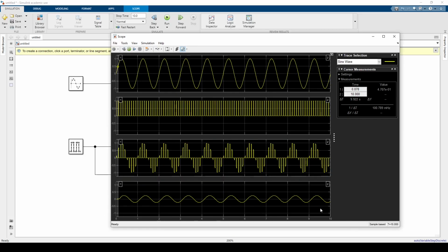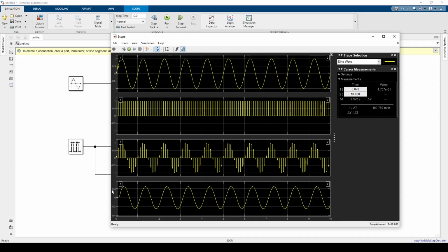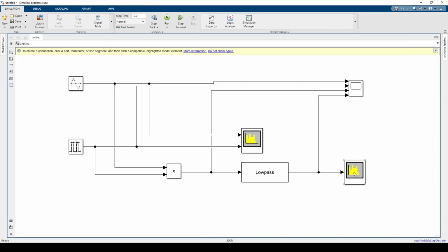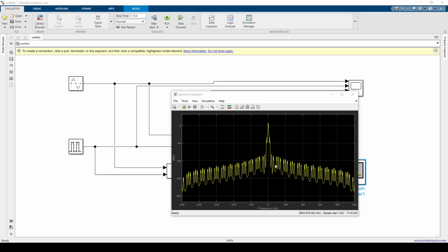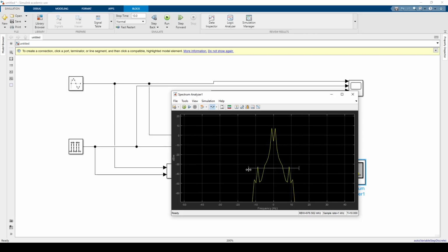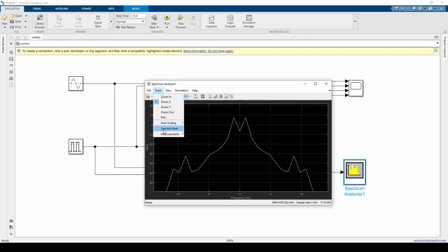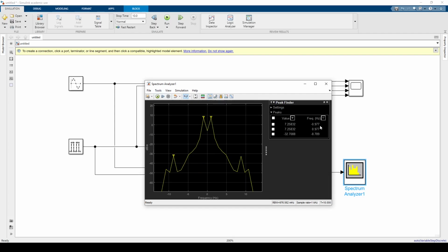This bottom plot is the reconstruction of the sampled waveform. The amplitude has decreased, but the period and the frequency is just about the same. And if we look at the spectrum analyzer, all of this is noise. It is less than -75 decibel milliwatts. So if we zoom in on this part, let's bring out the peak table, we just about get around 1 Hz, which is the frequency we started with.